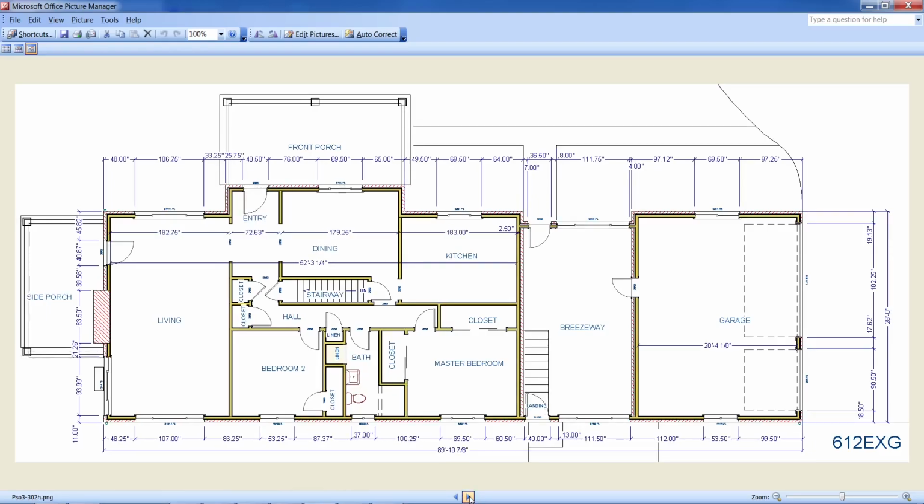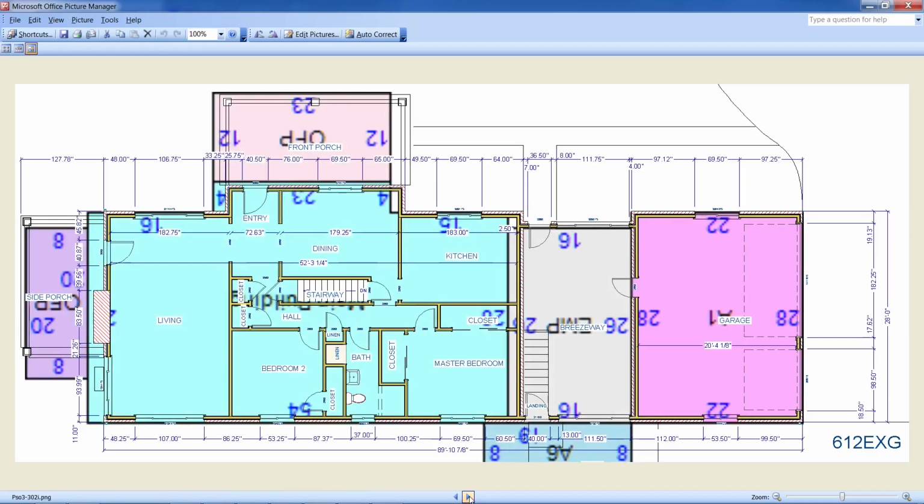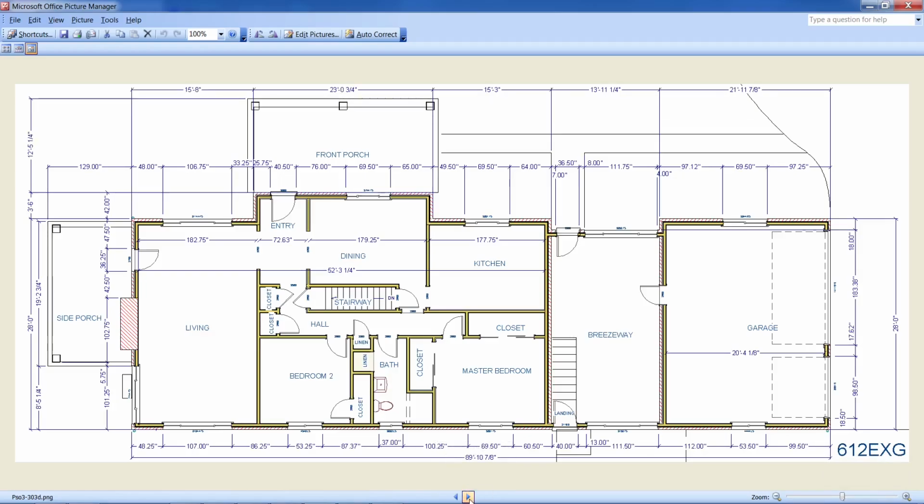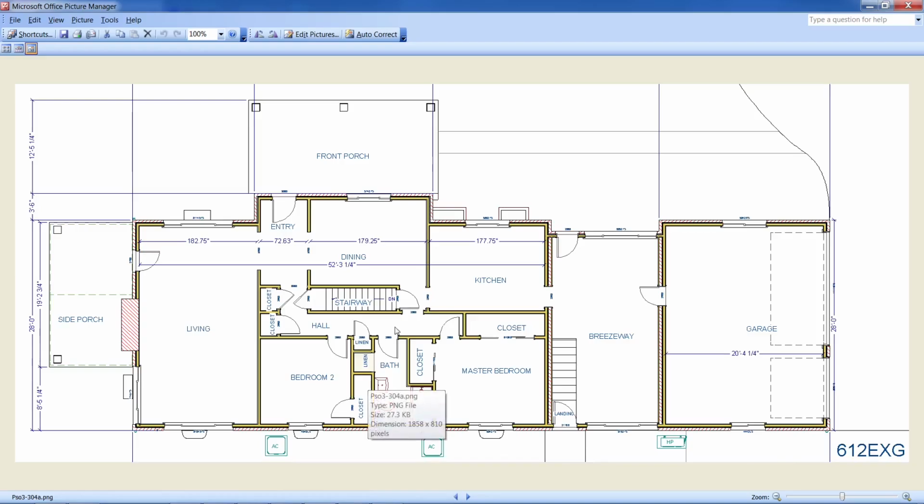So that adjusted the plan this way and continued to adjust it all the way around its perimeter based on those field dimensions I took, arriving at a pretty reliable model of the outside. And that's how it lines up with the county sketch. And so now it's renamed 6/12, June 12th, existing plan. And then I did some more adjustment on this interior based on photographs, and it starts maybe looking a little bit more like what you have there.